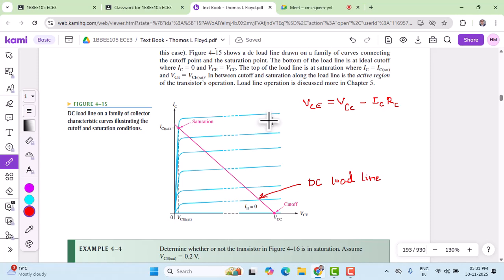We can add those two together. 15 volts is going to be the VC max, and the VRC is going to be 19.5 volts. That gives us VCC as 34.5 volts. So now VCC is going to be 34.5 volts.